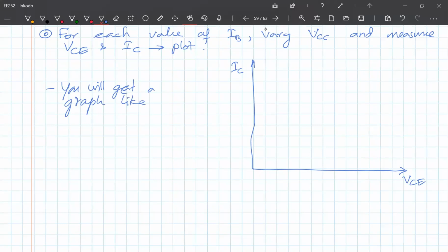Okay. So let's say I have zero current. Obviously, if you have zero current, there is not going to be IC in cutoff mode, so you will have something like this, almost 0. There is no current. There may be a leakage current. Remember, there is a leakage current. It is possible. So this value is IB equals 0 microamperes.